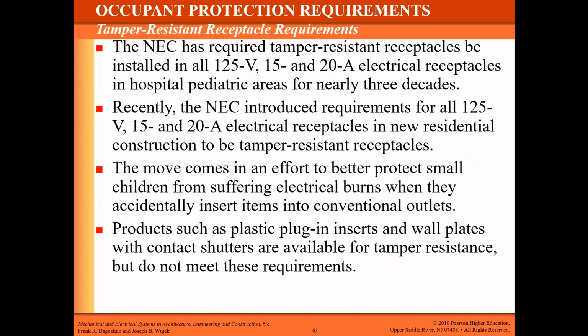Okay, let's bring it back to something a little more relatable. The NEC, the National Electric Code, has required tamper-resistant receptacles to be installed in all 125 volt, 15 and 20 amp electrical receptacles in hospitals, pediatric areas for nearly 3 decades. Okay, so this has been around for quite a while. Tamper-resistant just means that there's something inside the slots of the receptacle that prevents poking something into that slot unless both slots are being engaged at the exact same time.